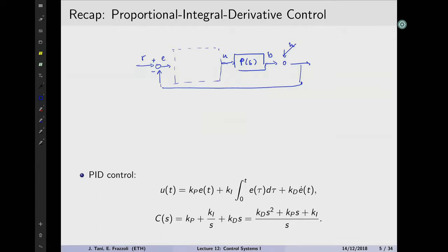And so PID says, just take the error, the difference between the reference and Y, and create the input signal to the plant as the sum of three components. I'll draw it here like a block diagram; the equations are below. The first one is a proportional term, so we just multiply the tracking error by a number. The second component is proportional to the derivative of the tracking error, so we multiply by KD and take the derivative in time of the error that comes in.